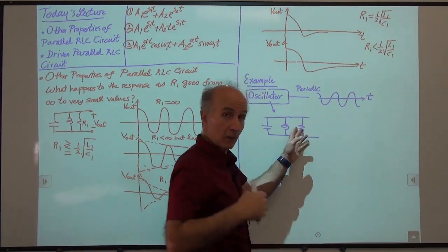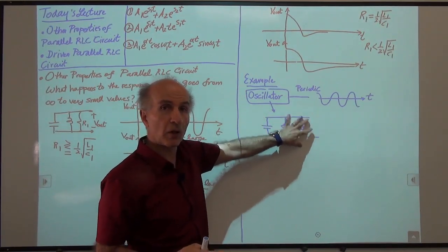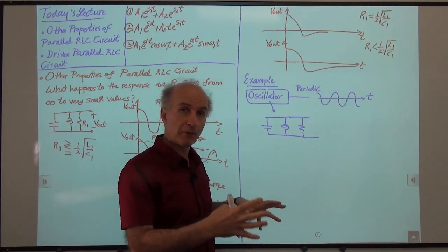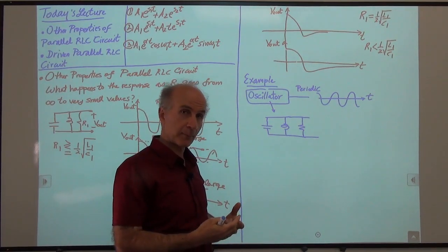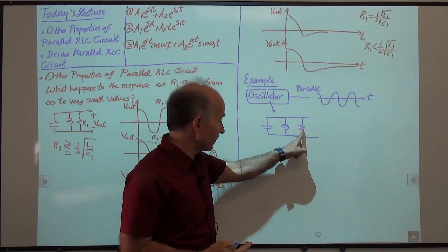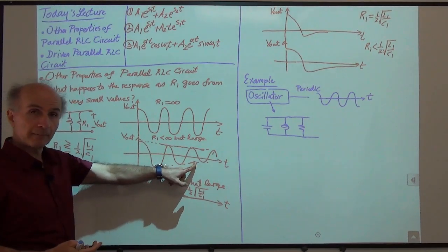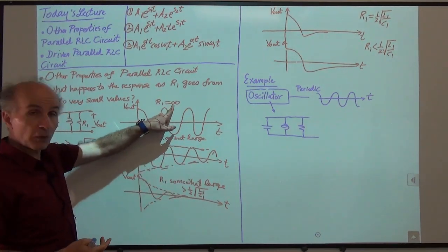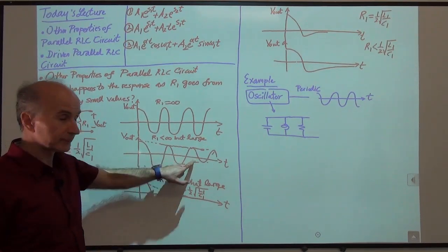It's not that we deliberately add that resistor, it's just that this resistor is actually part of the imperfections of this tank that we have built. All right, so here's the problem. This resistor causes the oscillation to die away. If this resistor were infinite, we would be okay. But because it's not infinite, we are losing the oscillation.